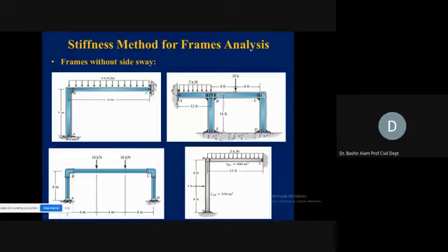At A, we convert this now into a roller support. So if we convert A, instead of the hinge support, into a roller support, what will happen? It is now unsymmetrical. If you look at the loading, it is unsymmetrical. So what will happen? Then there are chances that it can have displacement in the horizontal direction.